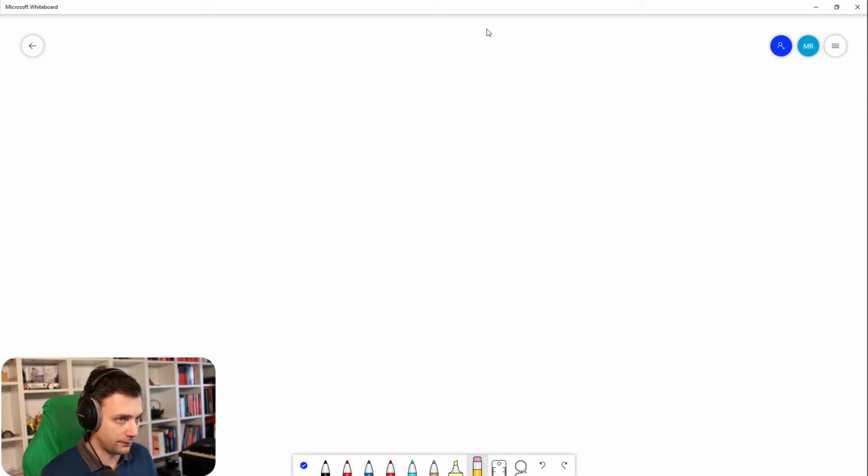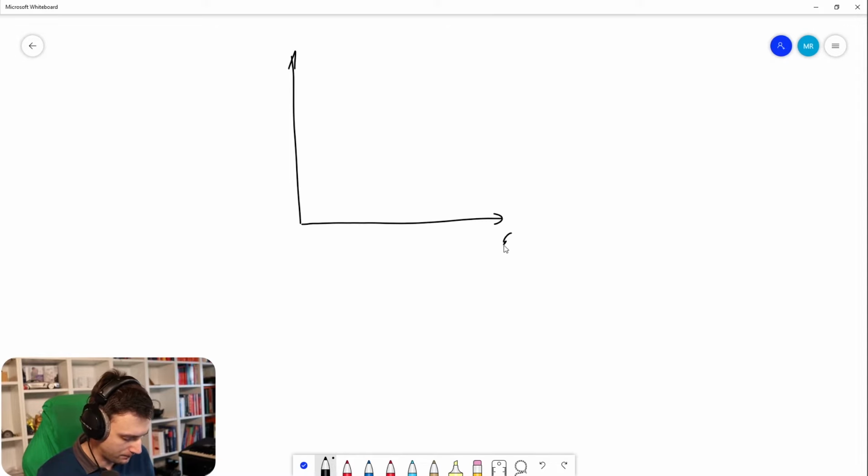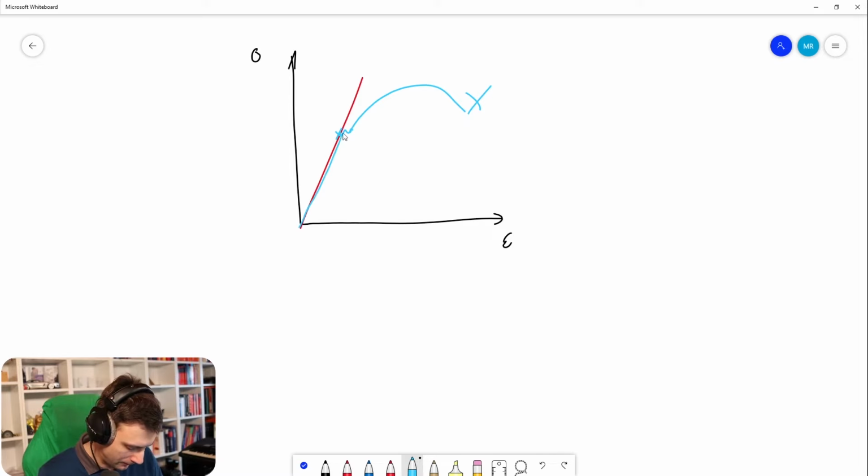All right, so after we talked about this a little bit, now let's focus on the main topic, and this is the material nonlinearity. So maybe you saw that a bunch of times, the stress-strain relationship. In linear FEA, you're valid on this line. If you go beyond the yielding point, which I will mark maybe here, and here's your failure. So if this is a curve, you're valid until this point with linear FEA. After that, it gets wrong.